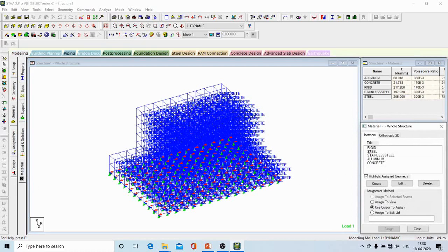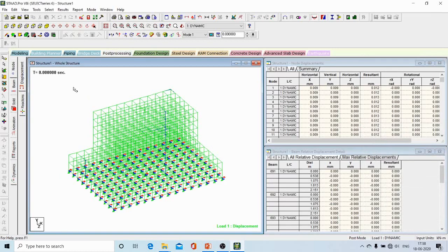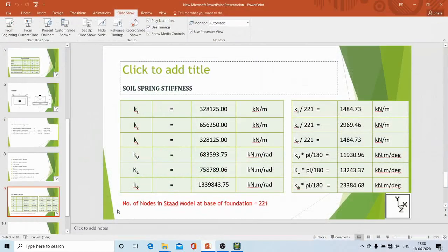So I will change it to rigid_beam because it does not allow the space in the name of material. So just change it and try it if you find any error. And so in this way, we can determine the natural frequency and amplitude of the machine foundation by finite element modeling. So that's all.